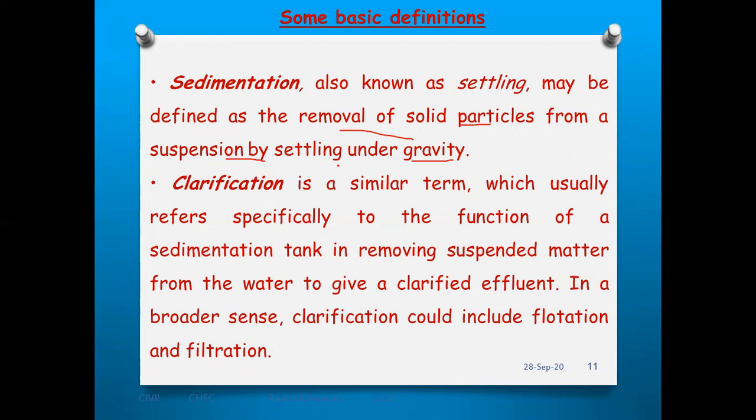So the large materials which come down and settle through gravity are removed from suspension. This is nothing but sedimentation. Next, clarification. It is a similar term which usually refers especially to the function of the sedimentation tank in removing suspended matter. So the term is specially used for the function of a sedimentation tank in removing suspended matter. Okay, right. In the broad sense, clarification could include flotation and filtration.